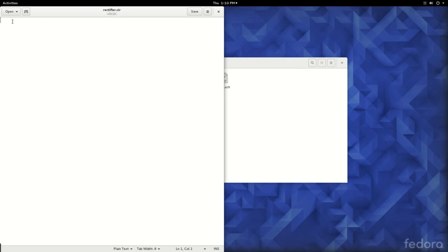And here, the first line is always a comment, so start from the second line. We would like to have a transient analysis performed, step time of 50 microsecond up to 100 millisecond using the initial conditions. Also include the rectifier.net. Rectifier.net is not yet generated, but we will shortly generate that. I will let you know how to do that.